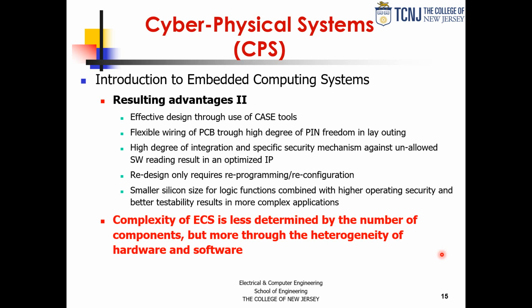Another opportunity for these methods is the idea of how to test the system. Because as complexity grows, ad hoc methods of testing actually reach a plateau. It's not that by throwing more patterns at the system, you can actually actuate all the different paths of functionality that the system may encounter eventually. So you need structured methods of testing, not only in hardware, for which a great deal of very interesting methods exist, like scan design and BIST, built-in self-test, but also in software.